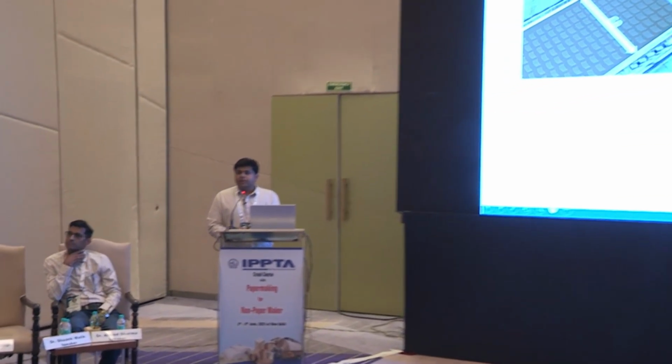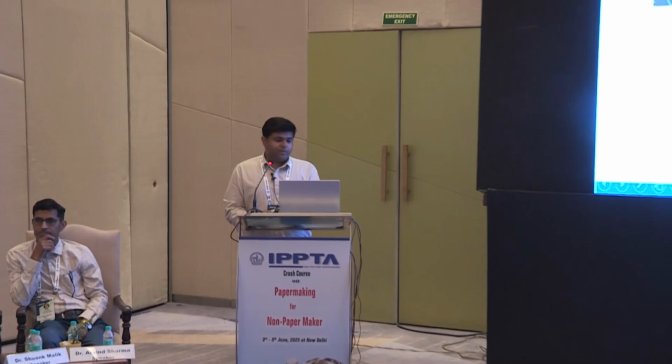So we have different possibilities to orient our fibers. In the first case, where the jet to wire ratio is more than 1, the fibers tend to orient themselves mostly in the cross machine direction. When the jet to wire ratio is less than 1, most of the fibers tend to align in the machine direction. And something in between, when the jet to wire ratio is 1, most of the fibers are randomly oriented. But we have a thumb rule that if this ratio is somewhere between 0.9 to 1.04, we can have paper with acceptable formation.